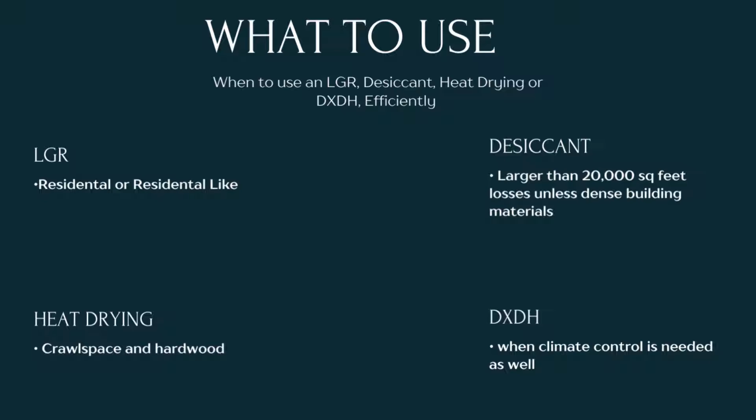When to use an LGR, desiccant, heat drying, DXDH, and their efficiencies. Let's talk about LGRs a little bit. Low grain refrigerant, I think you all probably know what those are and what they dry. Again, they're really good for small rooms. They're good in a residential setting. Usually you can put 2 to 3 in a house and get good dehumidification out of it, providing they're working okay.